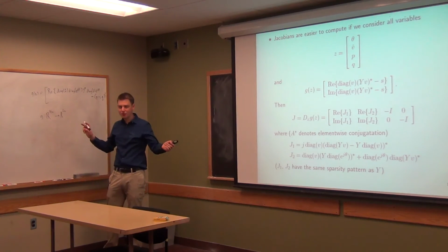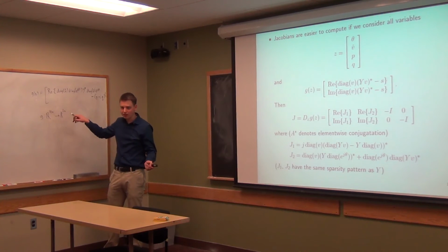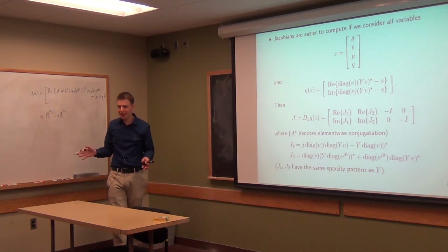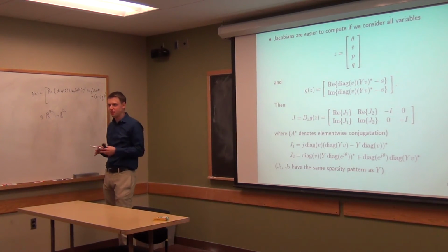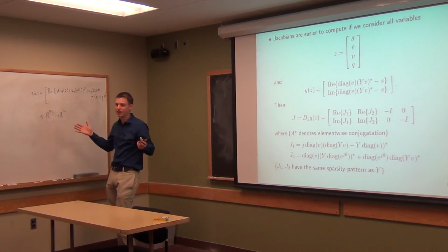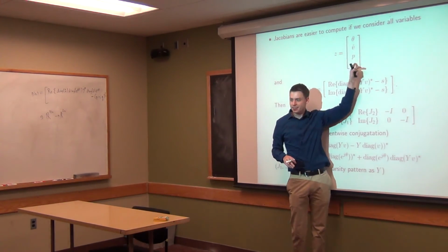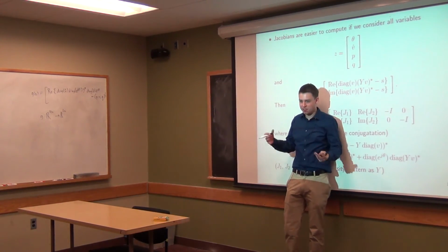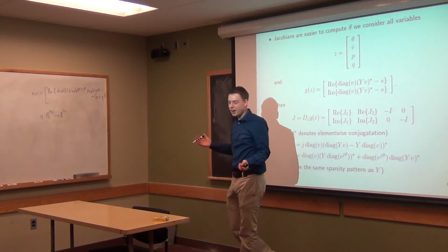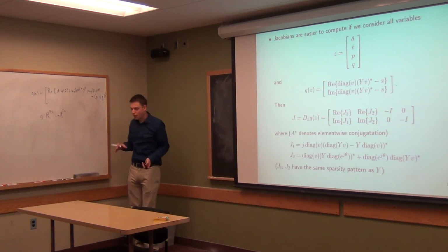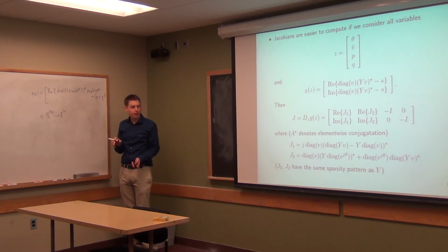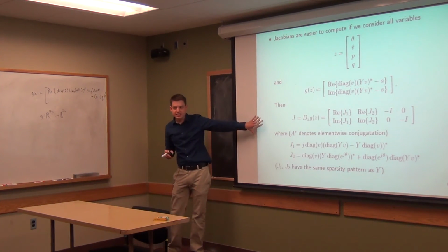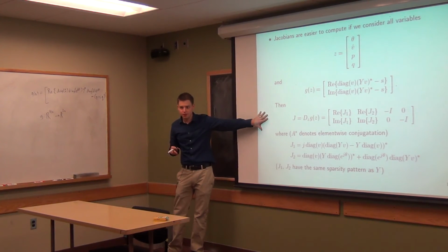We would have 4n unknowns and only 2n equations. We can find a lot of different solutions that have g equal to 0. And that just corresponds to basically every single possible power flow scenario you could have, right? If you can pick all the variables here, then of course you can find lots of solutions to this. That's just every single possible physical power flow. But what we do have in reality is we know 2n of those entries, right? So 2n are fixed.